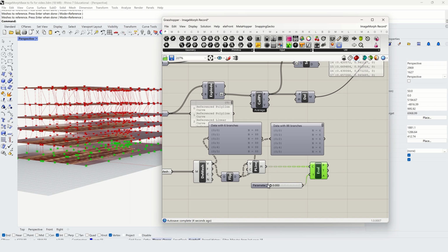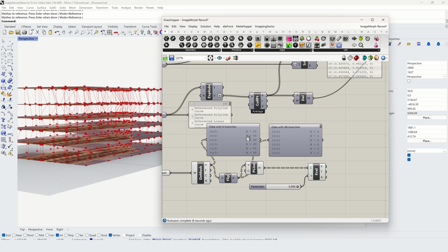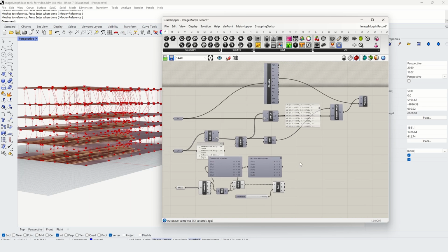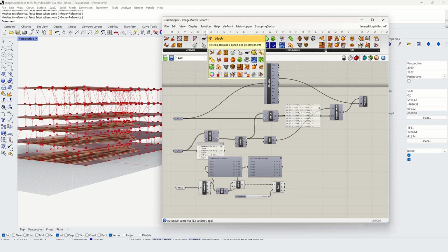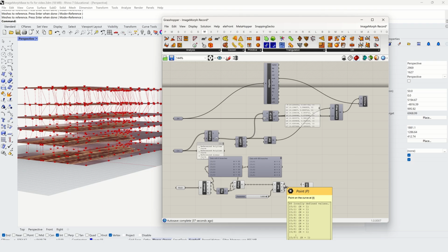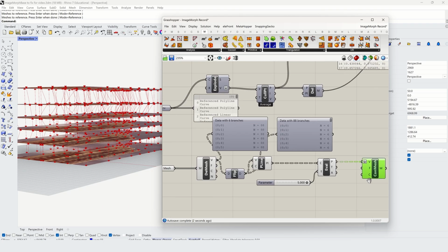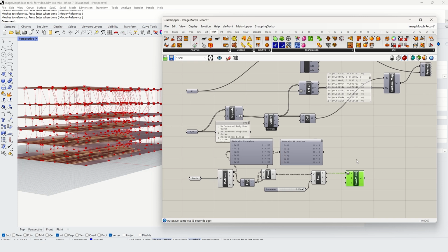Now it just remains to rebuild the mesh from these points. Construct mesh is the operative component. Supply the Evaluate Curve point outputs as the vertex inputs. Flatten this, because all the points should be brought together to make just a single mesh. The F input, faces, tells the component which vertices are connected to which others. Since this information never changes in this example, this can be taken directly from the earlier deconstruct mesh component, which gave face data as output.